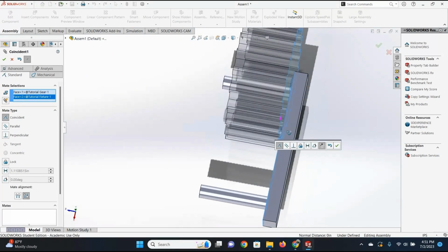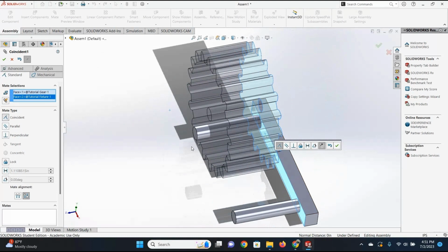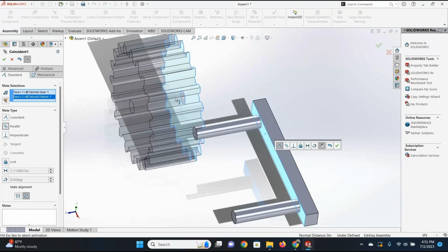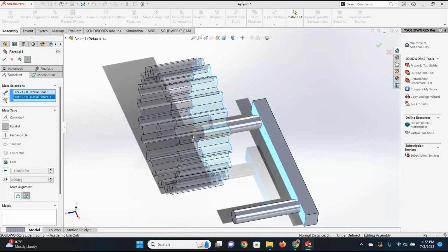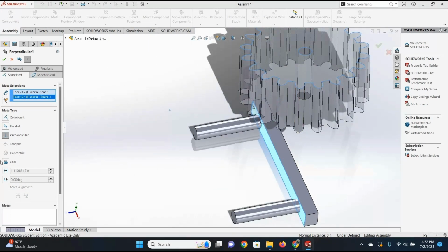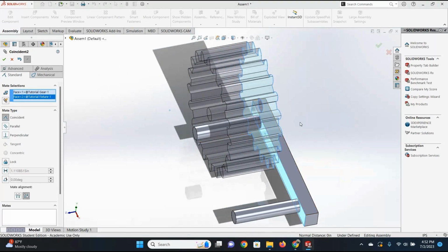And as you can see here, they are under the coincident mate type, which just means that they are coincidentally touching like that. We can also select that they are parallel, which would make it to where this part will go in a straight line according to this face, or we can do perpendicular, which will make it perpendicular to that face, or lock, which will lock the geometry between them. But we want to do coincident in this situation because we want the faces to be touching.